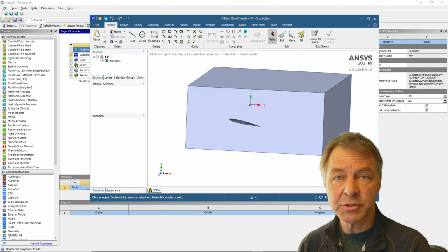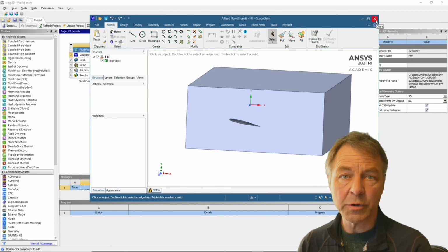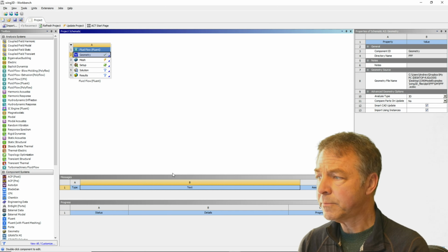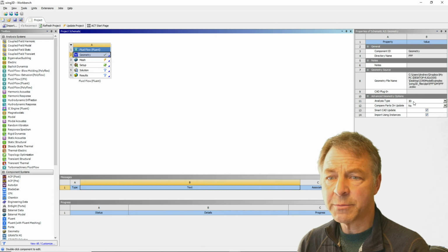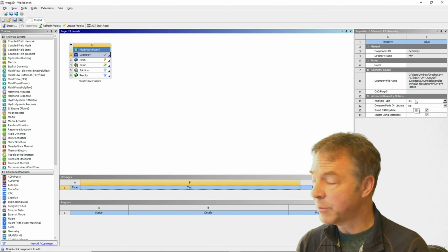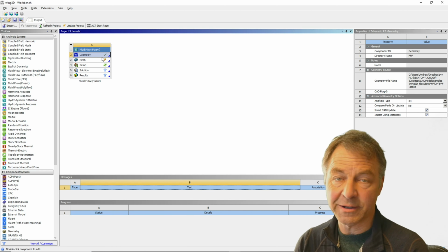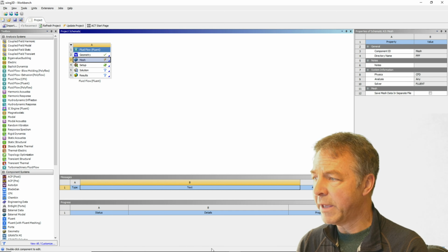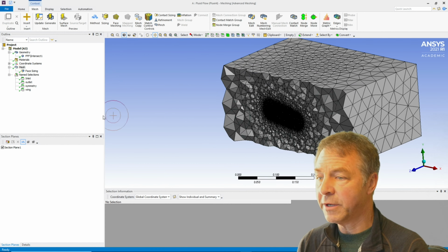So for ANSYS, you need to create the volume of fluid. And once you've done that, then you can work on the simulation. So I'll just close that. Now, I've already loaded it into Fluent. I've loaded the geometry. I've specified, in this case, 3D here. And this is important because we're not going to do that later. And if I then go to the mesh, I've already got that open, so I'll just pop it open here.